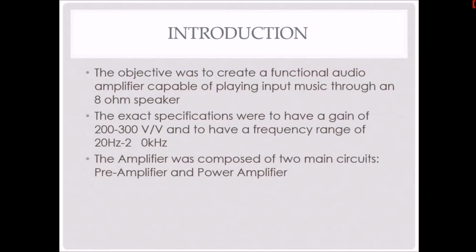The goal of this project was to create an audio amplifier capable of creating 200 to 300 volt per volt gain and a frequency response in the audible range, which is about 20 Hz to 20 kilohertz. It was split into two parts, a preamp and a power amp.